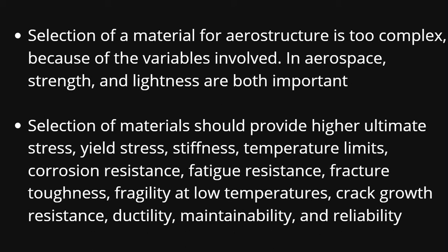Some materials have some of these properties, but aerostructures need all the important positive properties to be available in the material. So we need to look at criteria like stress, yield stress, stiffness, fatigue resistance, and crack growth resistance. Ductility is very important.